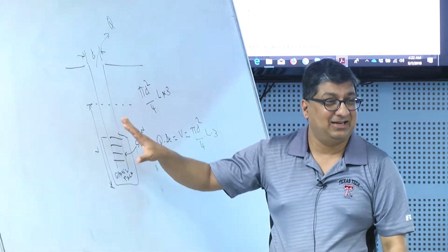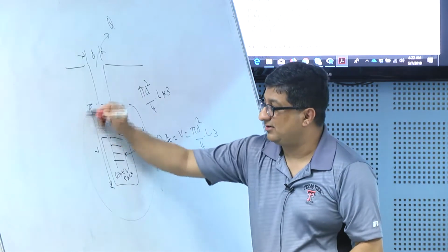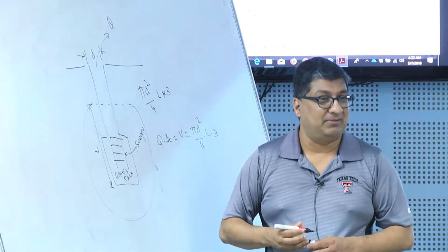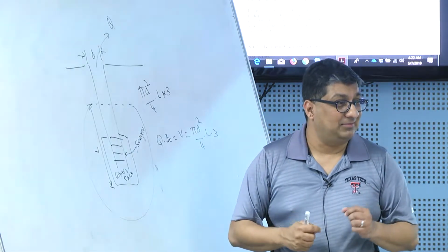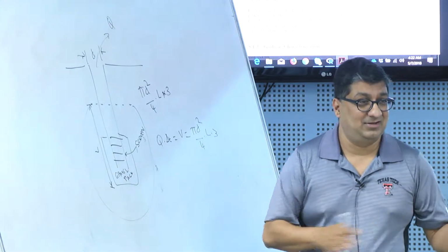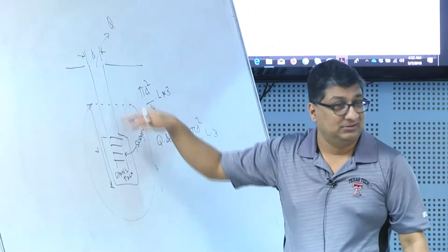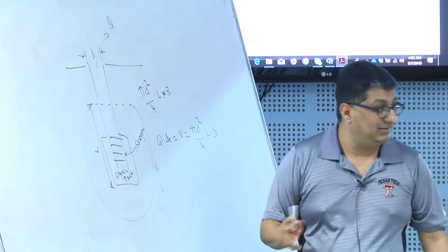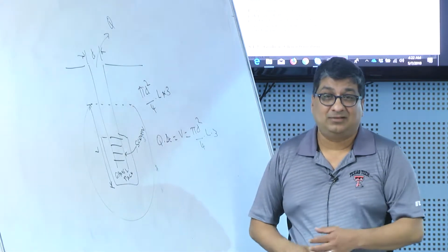So I'm getting truly a sample from the aquifer as opposed to a sample from in the well, because the water in the well's chemistry is going to be very different from the chemistry in the aquifer surrounding it. And we want to see what's happening in the aquifer. We don't want to know what's happening in the well. So it does provide that.